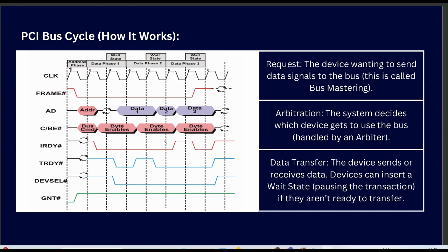Sivam, sorry to interrupt you. Basically, don't relate this PCIe and PCI. Both are different, right? As you mentioned, PCIe is serial communication, and this is parallel communication. So you have to put some hardware in between that converts serial data into parallel form and parallel to serial. We will cover this when we come to topology.